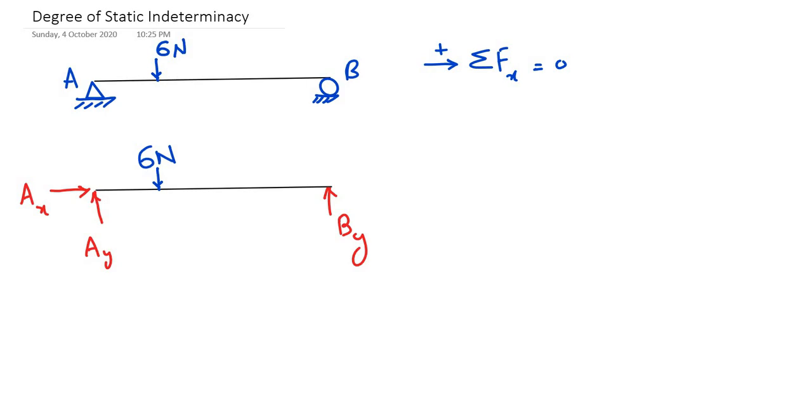So looking at this free body diagram, you know that we have only one force acting in the horizontal direction, in the x direction. Although I didn't mention it, let me mention here that I'm treating x and y in these directions. These are my x, y directions. Based on these directions, I'm showing this as BY, this is AY, and this is AX. So I have some coordinate system for this. Rightward positive. This is an external force, AX.